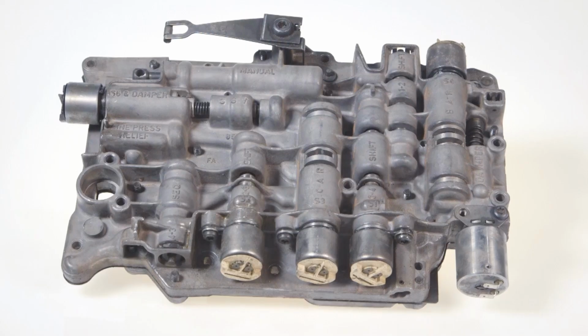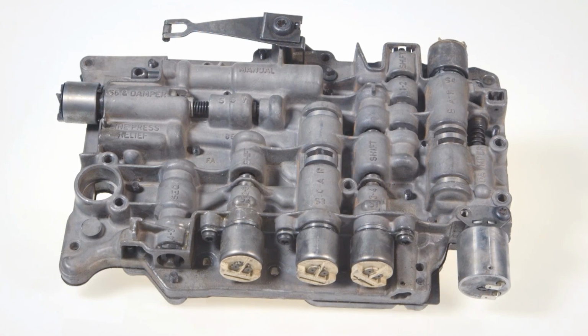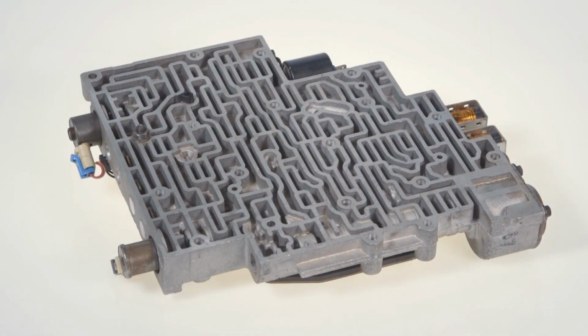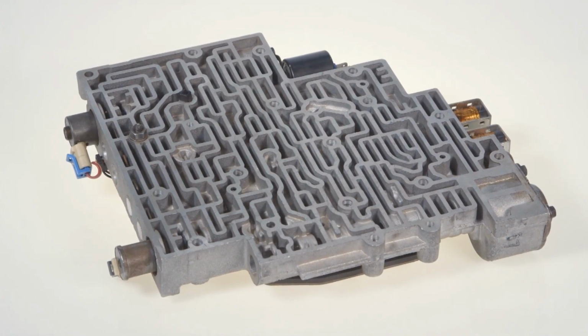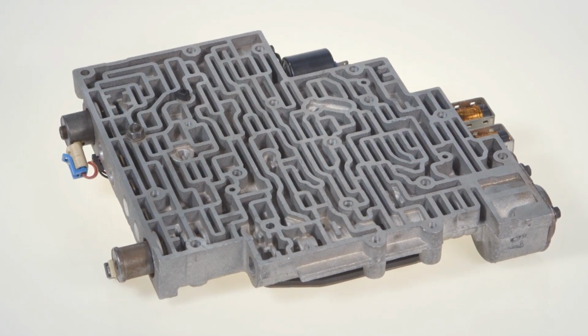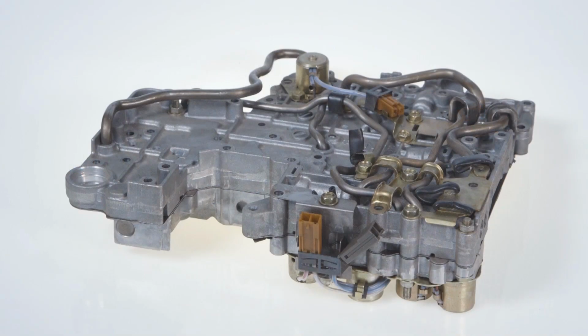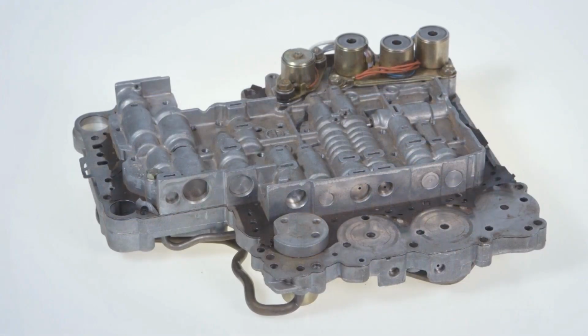In order to understand the principles of hydraulic control, we need a strong knowledge of how an automatic transmission's hydraulic circuitry and valving operates. All automatic transmission systems have a valve body comprising of numerous passages and channels which direct the flow of hydraulic fluid throughout the transmission. A special hydraulic fluid is directed through these galleries to different valves in order to activate a clutch or band, which in turn selects the appropriate gear for the current driving conditions.